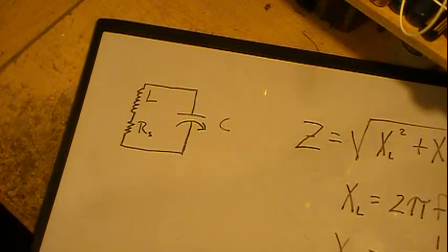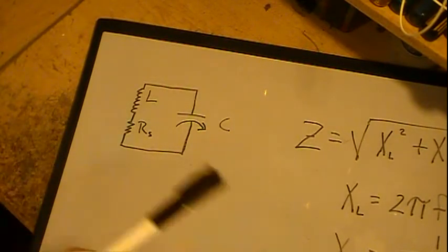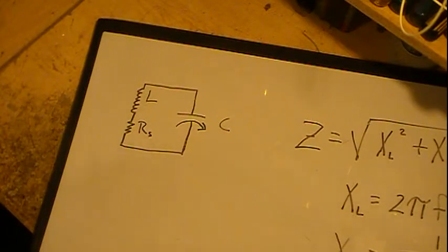Sometimes coils can have a break right at the very end, where you can just clean it up a little bit. Maybe you might have to attach a little bit of wire to it and resolder it back on. A lot of other coils, unfortunately, are broken somewhere in the middle of the coil. May even have two or three breaks. So in any case, you're going to have to rewind the coil.